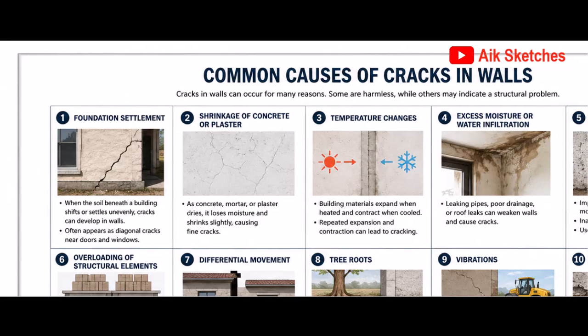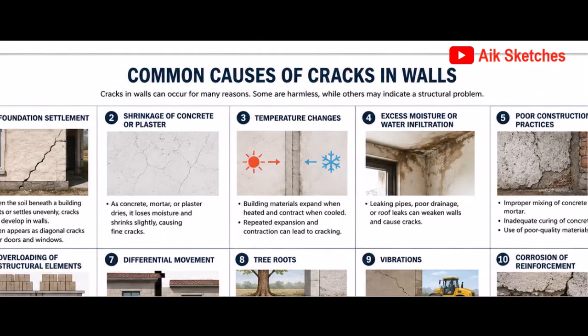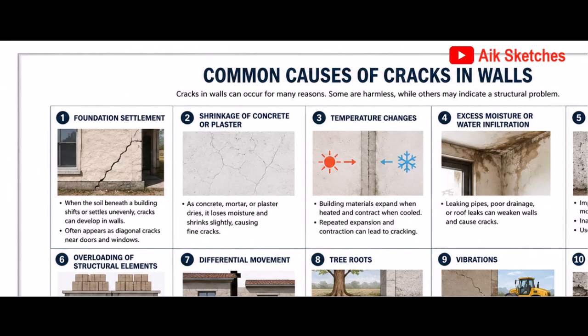Let's go to the next one: poor construction practices. Improper mixing of concrete or mortar can cause cracks in the wall. Inadequate curing of concrete and use of poor materials can also cause cracks on the wall. It's important that we take note of some of these things so that we can avoid cracks on the walls.